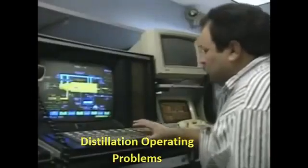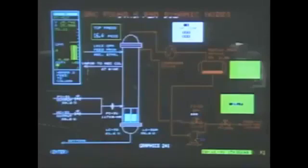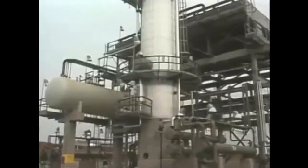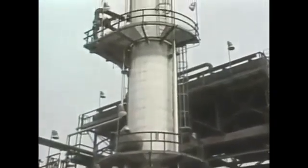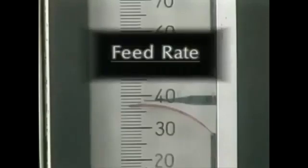A distillation system is designed to operate within certain predetermined limits. But when problems occur, efficiency and product quality can suffer. Operating a distillation system involves maintaining an equilibrium or balance between the rising vapor and the falling liquid in the column. One aspect of operation that can affect this balance is the system's feed rate.